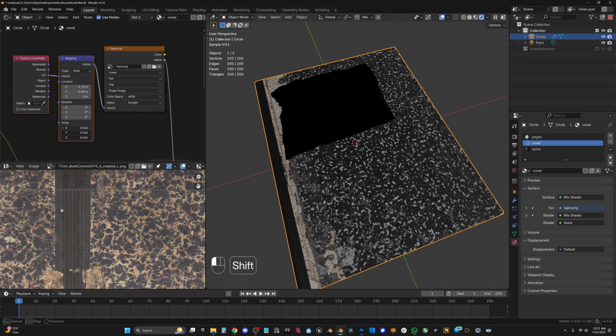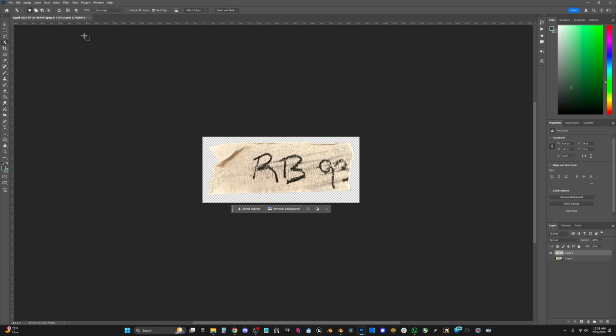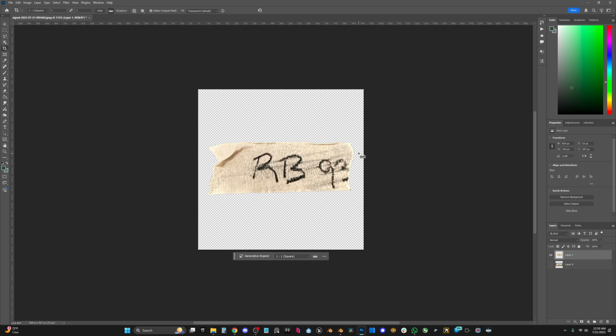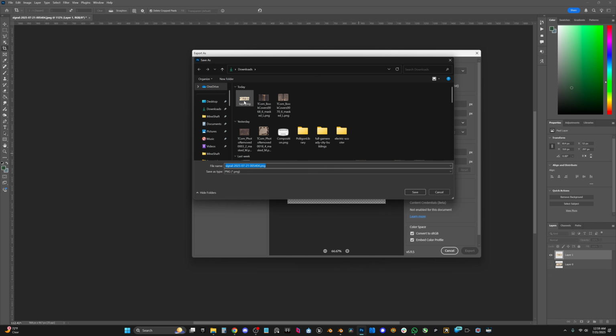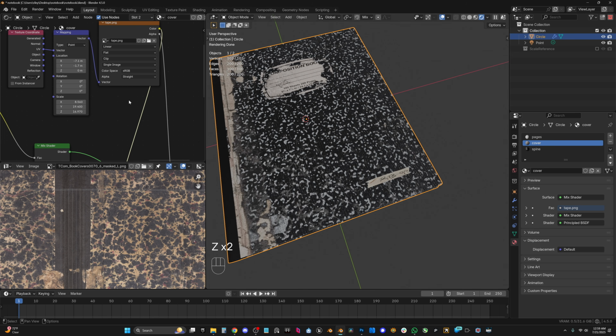We really should be exporting textures on a square aspect ratio so we don't have to eyeball things. Let's do what we should have done before. Let's crop this, but let's tell it to be 1 by 1 square. This is going to be a lot cleaner. So let's export that again. I hit Control Shift Alt W to export quickly in Photoshop. That's quite a shortcut. And let's just go solid and then rendered view so it refreshes itself. And now this should actually be the same number all the way through. There's no guessing. We can rotate it without it screwing up the aspect ratio. That's just going to be a lot nicer to work with.